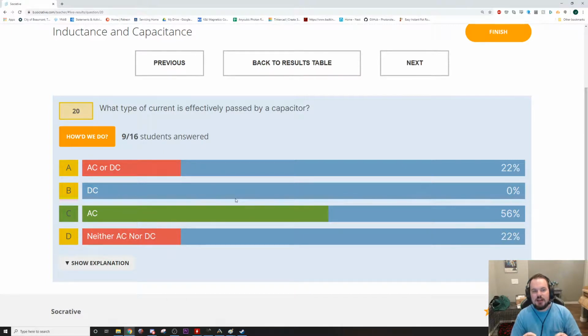It starts getting harder and harder to charge the capacitor the higher the charge goes. So if you're never hitting that hard stop, if you're only playing in the 50% range, because as soon as it hits 50%, it's discharging and going to the negative 50% range, constantly going back and forth, it's going to be a lot easier. It provides a whole lot less opposition to the flow of current.